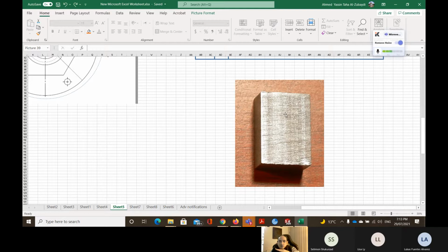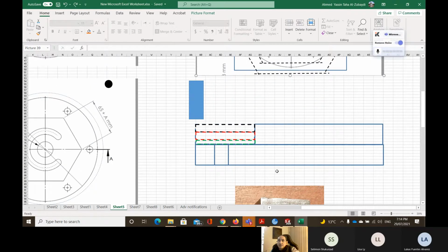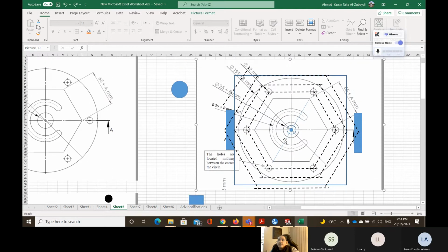One of the reasons that we need to remove a layer of 1 millimeter from the top is that this part has been cut using the saw, and to get a good surface we need to remove a layer from the material. So if the final thickness of your part is going to be, let's say, 20 millimeters, cut the part to 22. You're only going to remove 1 millimeter from above and below to get the final thickness of your work part. That saves you energy for the machining, saves you machining time, and saves some waste of the material.